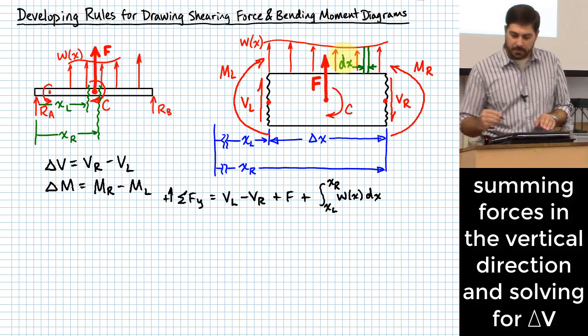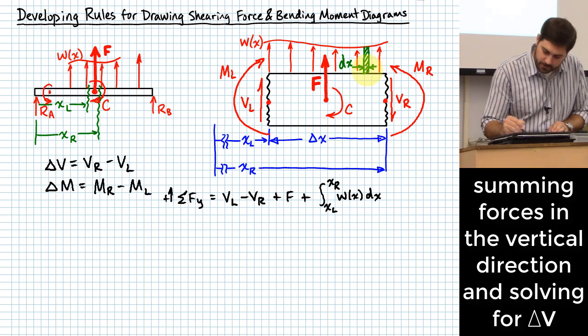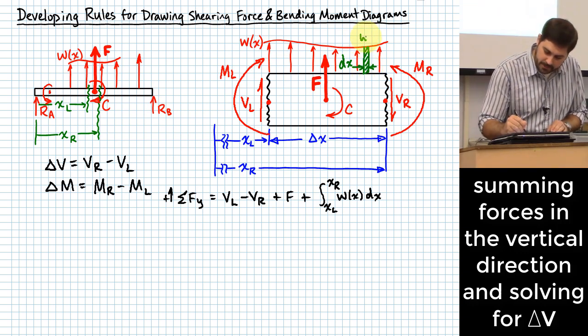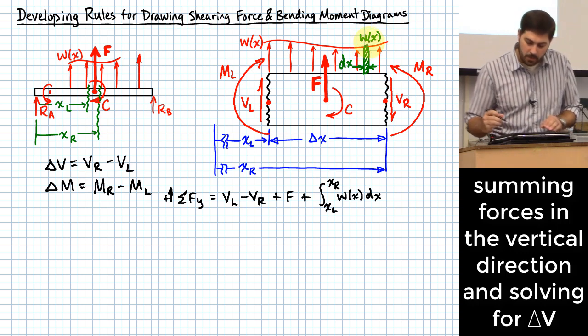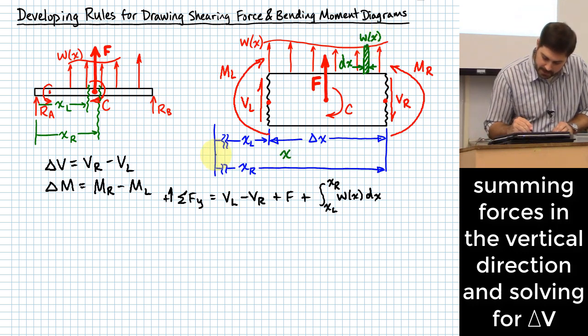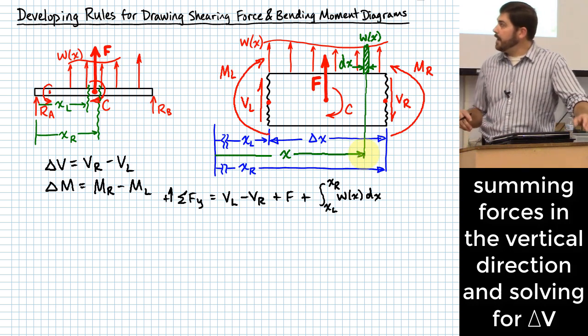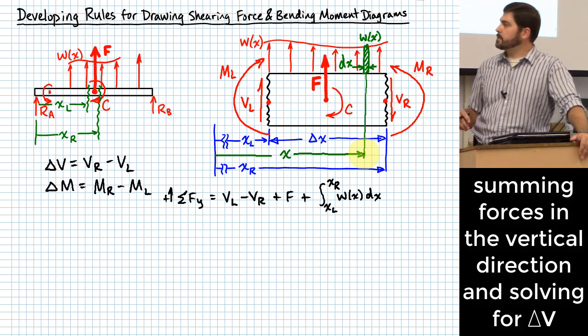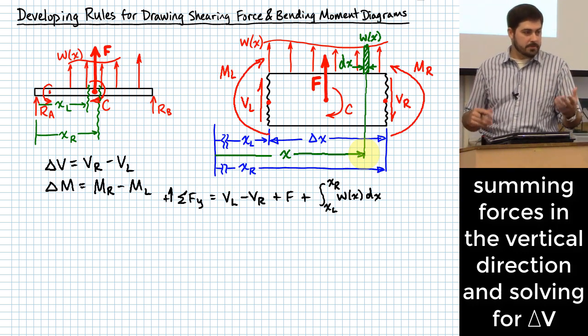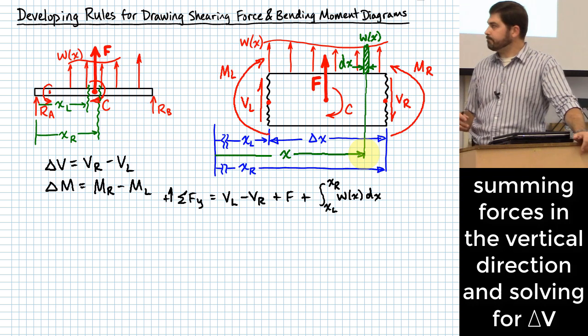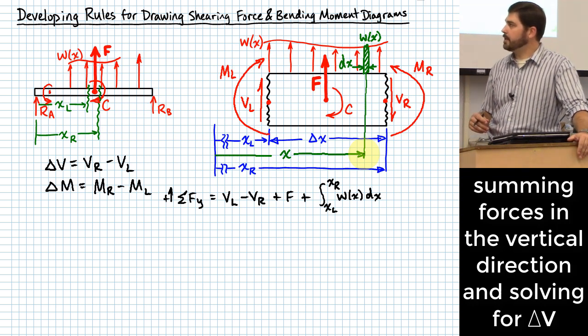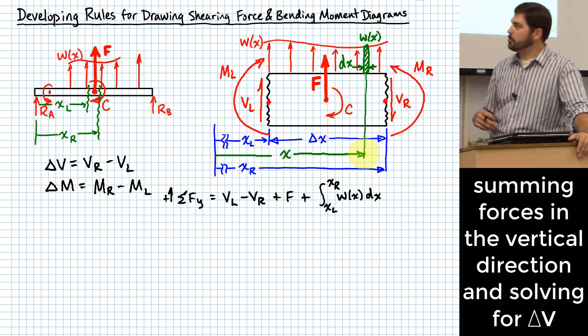The height of that little rectangle is going to be w of x, right here at this point, where x is now the specific coordinate that I am measuring relative to this specific location where I found that little rectangle. And you look at that, the area under that w of x curve is basically the total amount of force, which is why that integral is how we would evaluate the total amount of upward force due to the w of x curve.